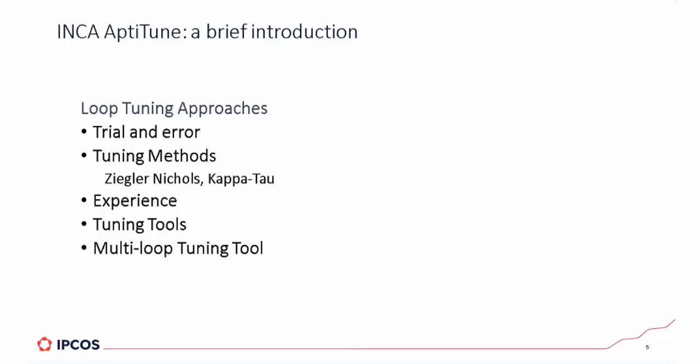Now, if you do this work more and more, an experienced project engineer, experienced control engineer can give you an estimate of what the proportional gain should be like if you tell him what the gain of a certain transfer, a certain curve is. If you increase the valve position by 1%, if you tell him what that does to the flow, he can give you an indication of what the proportional gain is going to be already.